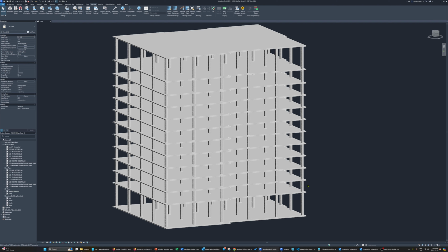Once again, it's a debatable science, but nevertheless, we still go through the process, and obviously we have to do it manually most of the time. So you're going to take a PDF file, you're going to take an AutoCAD file, and you're going to scale things left and right. You're going to measure the perimeters of the objects, and then you're going to multiply times the height to get the square footage of the surfaces that are in question, because obviously formwork has to go all around.